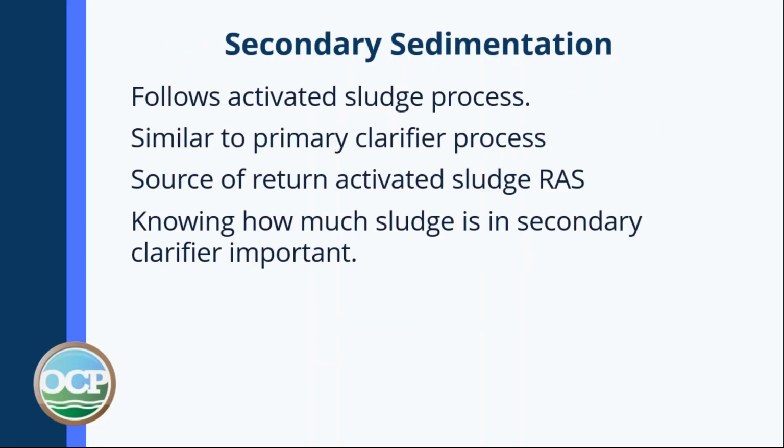Secondary sedimentation, we're finished with phosphorus and nitrogen. Now we're talking about the final clarifier. It follows the activated sludge process. It works similar to the primary clarification process. It's the source of return activated sludge. Knowing how much sludge is in the secondary clarifier is important.